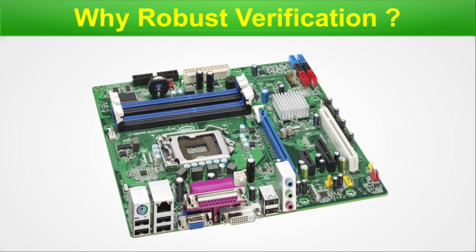need robust verification. Because from the beginning days, you know about the truth table. You will say, okay, we have a truth table and the device will operate in a standard defined way. However, in real life, when a chip is plugged into the board and the board has so many components that bombard data and address in multiple directions from multiple sequences, the design can crash. And the target of verification is that we make sure at what time and under what condition this DUT, that means your block or the full SoC, can crash. So we have to crash it. That is the purpose of verification, and hence we need a robust verification plan.